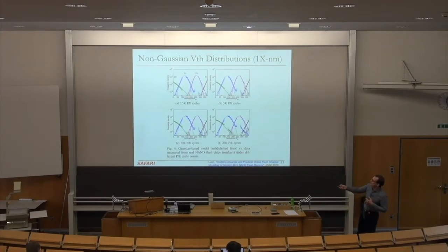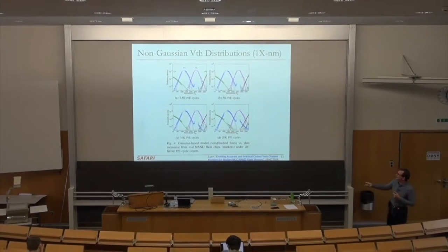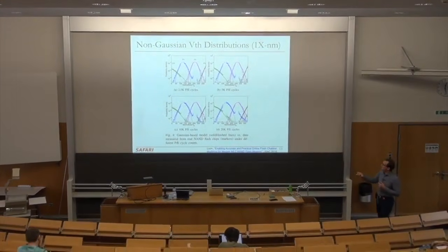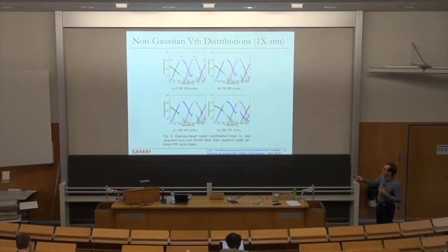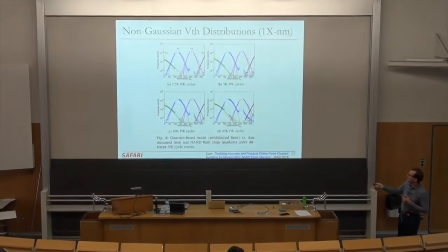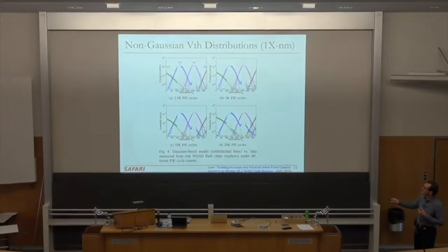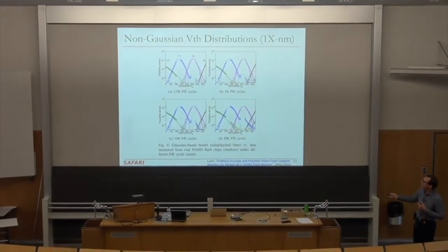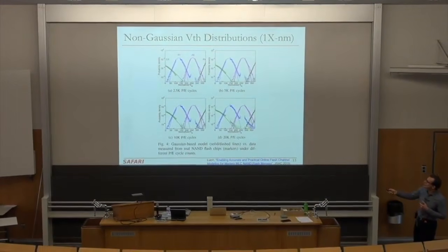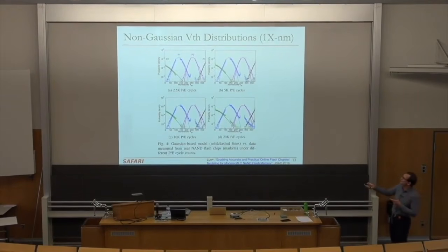But this is at 2.5K programming erase cycles. Once you're at 20K programming erase cycles, it looks like this. Now, a Gaussian model is not good at adapting to these sorts of discontinuities, or multiple peaks in the distribution. As a result, you would not get this part of the distribution correct. In fact, you're not getting that correct in many cases over here. That's true for some of the other ones, but the blue one is the most severe one in terms of the inaccuracy in the distribution.